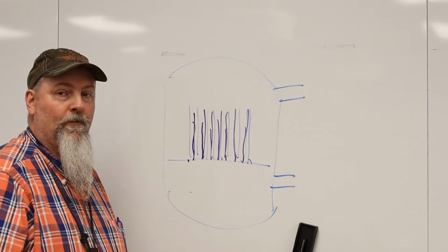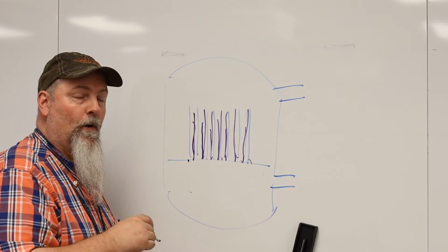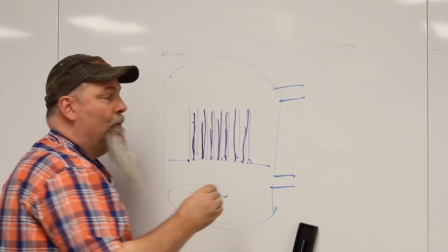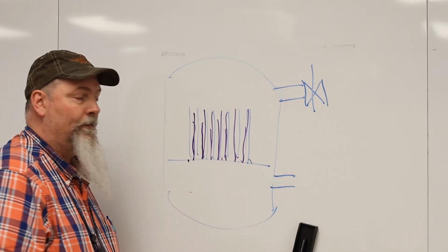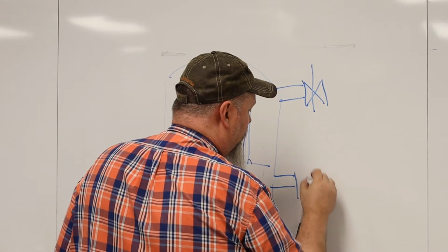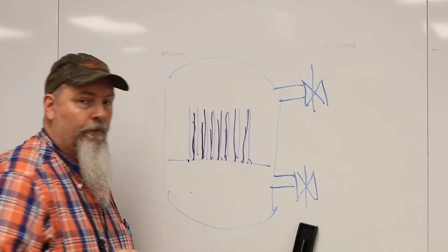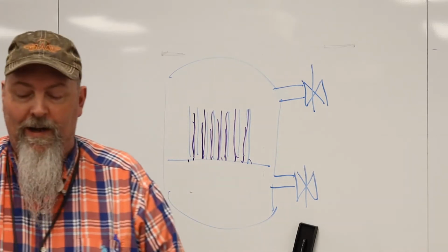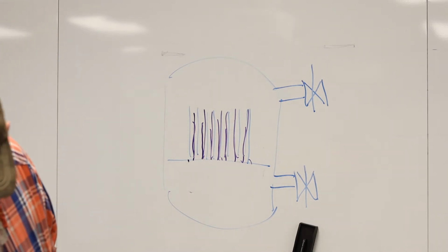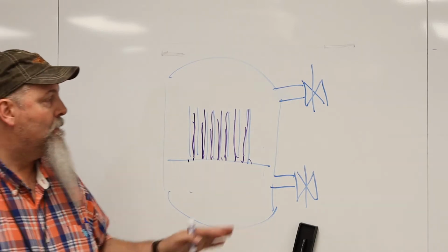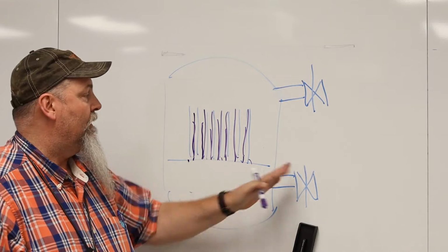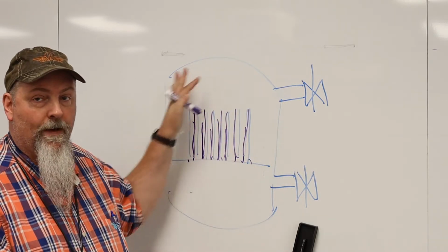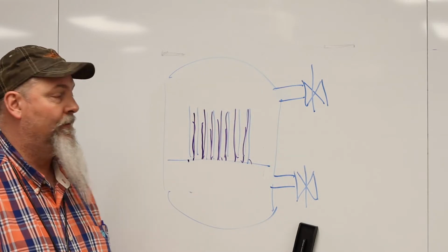And these pipes, for feed water in, for steam coming out, have isolation valves. So in your text where it's talking about an isolation, we're talking about the automatic closure of these isolation valves that lock the energy in the reactor pressure vessel.